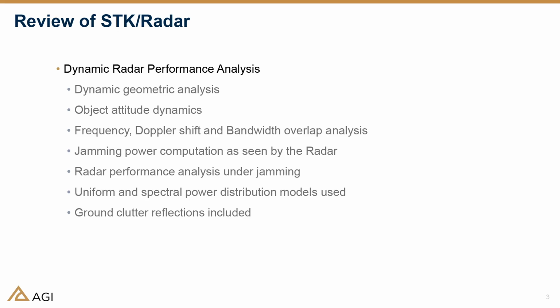One thing within STK radar is also the ability to use either a uniform or a spectral power distribution model. When you use the power distribution model, you have increased fidelity, which means a bit more calculation time. But along with that, you have a better idea of the shape of the signal as it is coming in. Of course, as we add more and more effects within STK, the fidelity will increase, but so will the computation power, so you just have to make sure that your machines are able to handle that.